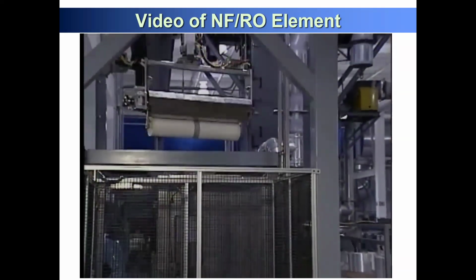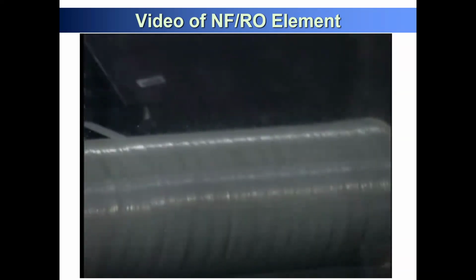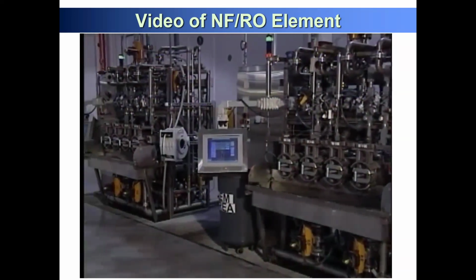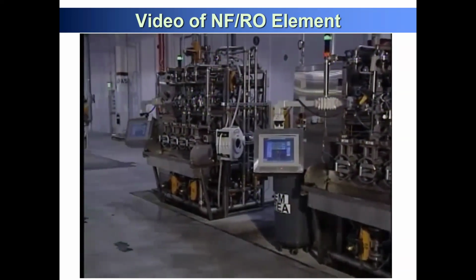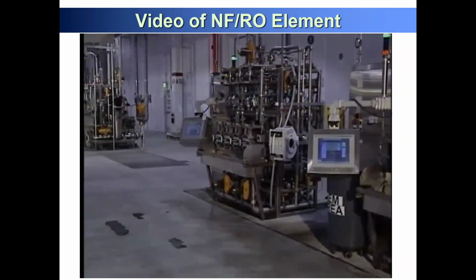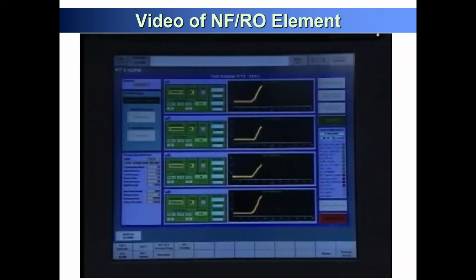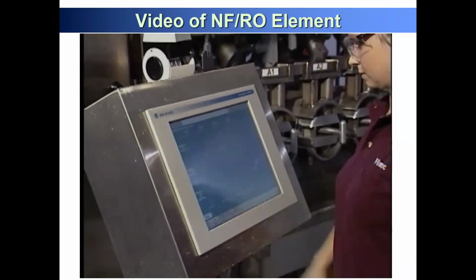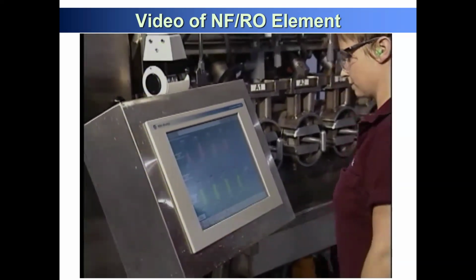Our automated fiberglass process ensures exact and uniform fiberglass application within controlled dimensional tolerances. To validate final element performance, FilmTech uses both a traditional 20-minute performance test and a groundbreaking pulse integrity test, which has the unique ability to detect and diagnose mechanical defects. Tests are computer controlled, and elements not meeting defined test ranges are discarded.